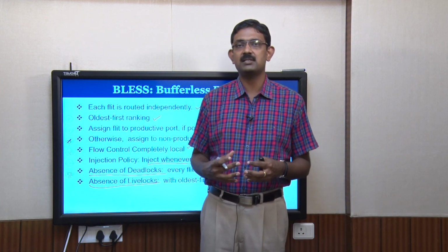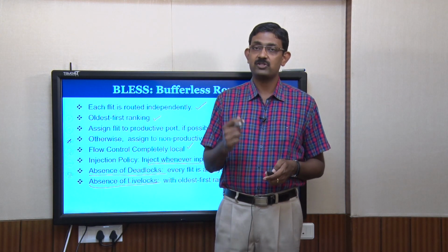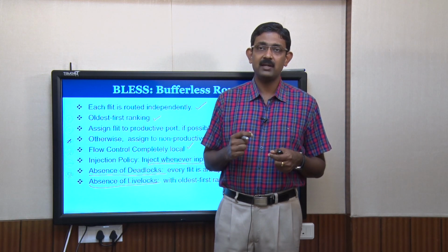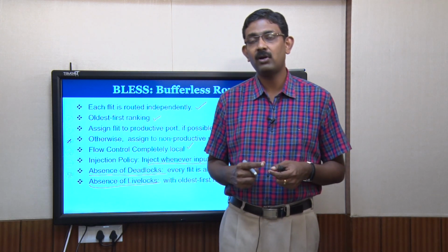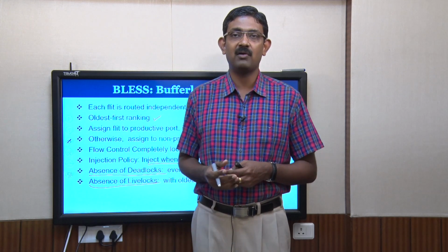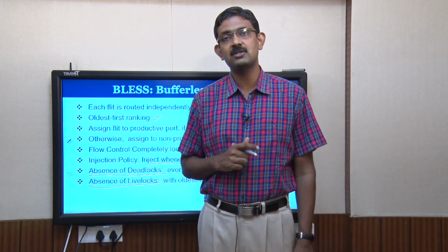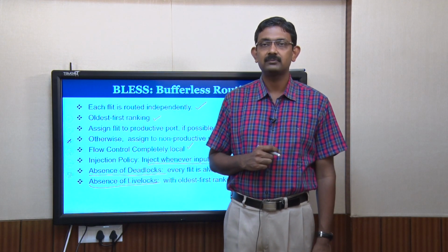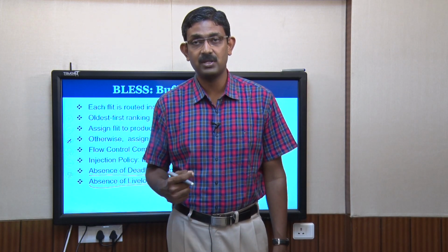So, I wanted to emphasize 2 aspects of bufferless routing. First one is, it won't create any deadlock. Deadlock happens because there exists a cyclic dependency for resources. One router has to wait for another router to get a buffer. Since the concept of buffer itself is totally eliminated in bufferless deflection routing, a packet inside a router is not waiting for availability of a buffer in the downstream router.